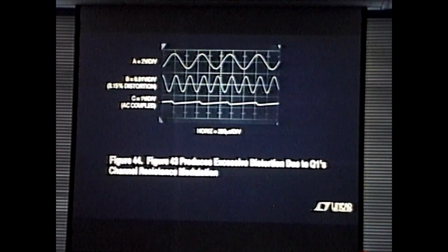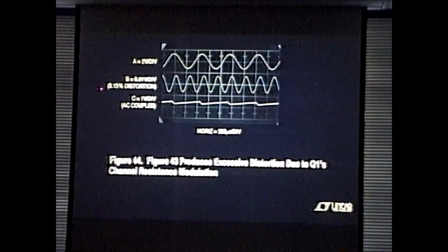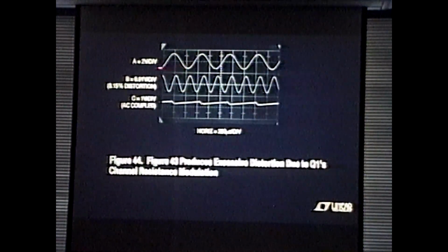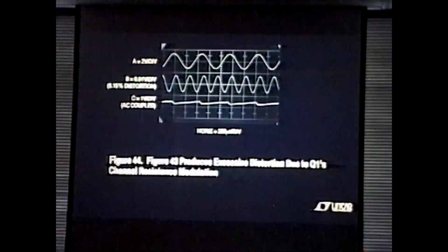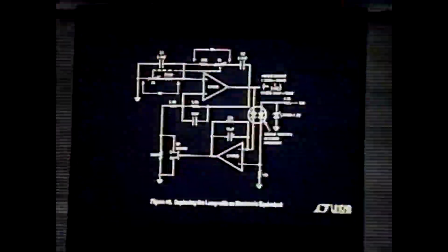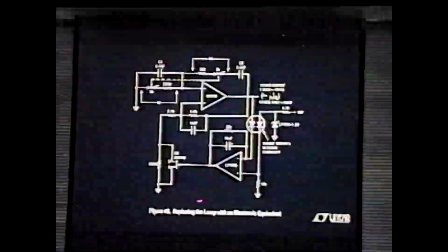What do we get for our trouble? What we've successfully done is increase distortion by a factor of 50. So we replaced one little old light bulb with 15 electronic components and made the circuit worse by a factor of 50. So much for modern technology's contributions. Why? What's going on in this circuit that unleashes such a dragon to kill 30 parts per million distortion from a simple light bulb into 50 times worse numbers with all this electronic garbage in here? Where's the billing? This is a device level problem, all you IC people.